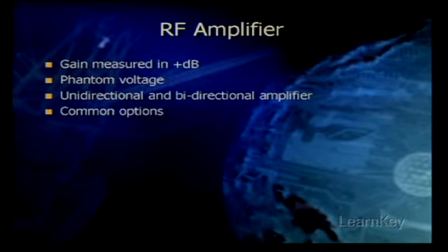There are some common options that you'll see with radio frequency amplifiers. Before you ever decide which amplifier to purchase, you should already know the amplifier specification requirements. Once you know what the impedance in ohms, the gain in decibel, the frequency response, which is the range in gigahertz, the VSWR, the input, and the output specifications, you will finally be ready to select the RF amplifier.